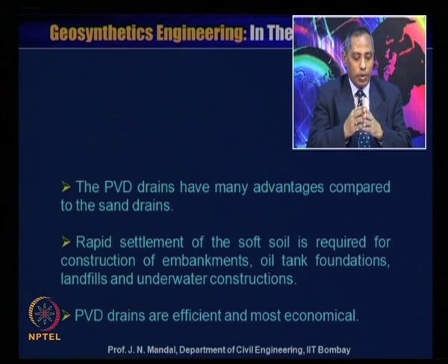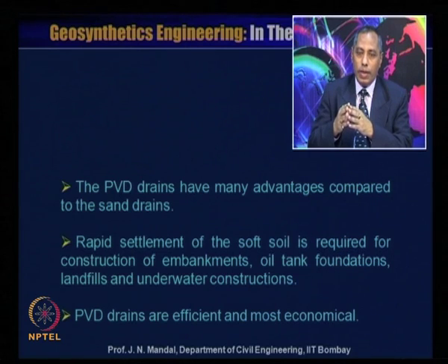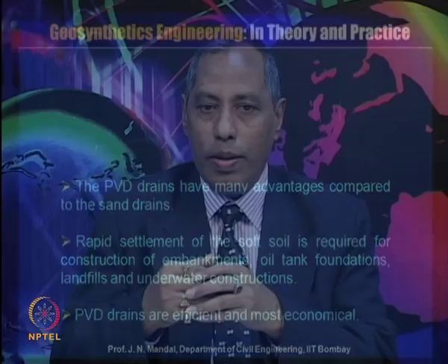But it is sometimes difficult to obtain the material on the spot, and also it will be very expensive. But in case of the prefabricated vertical drain, it is efficient and most economical with respect to the sand drain.